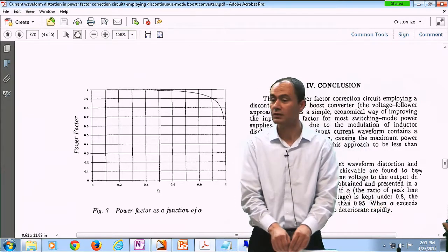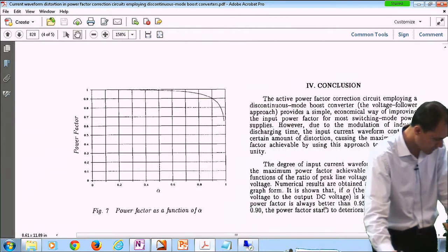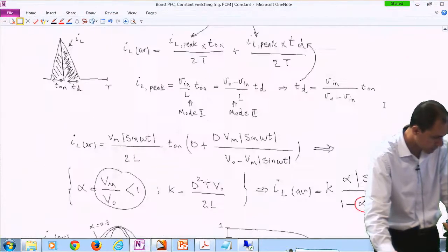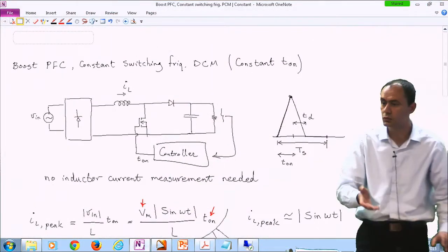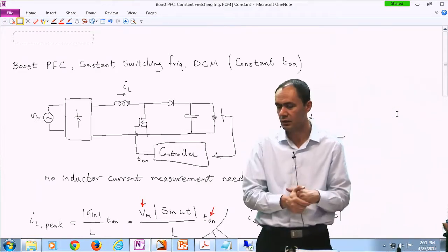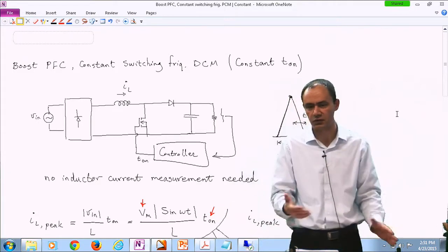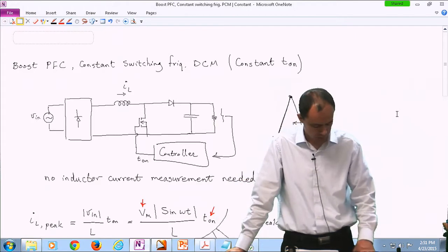Or you can use even a buck converter. As I said, your input current is distorted, but hey, what can you do? This is the best that you can do. You can use a direct buck converter to just step things down. But when your input is smaller than your output, the buck doesn't function, therefore your input current is almost zero. So input current distortion is relatively high.